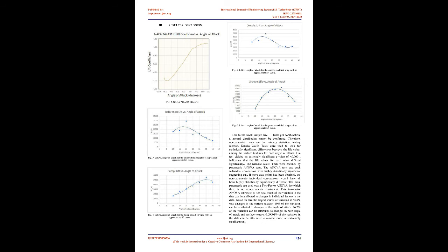At speeds of Mach 0.3 and above, models that treat air as compressible flow adhere to real-world performance better than incompressible models. Thus, compressible flow was implemented in the analysis. To mimic open-air conditions and allow for the software to account for the turbulence induced by the surface textures, we incorporated a K-epsilon turbulence model into our analysis.